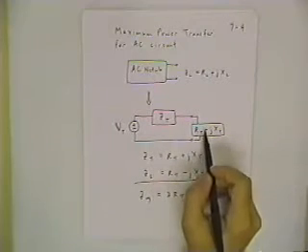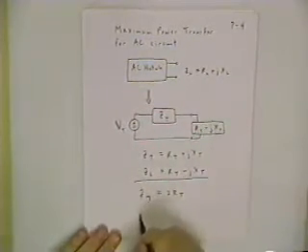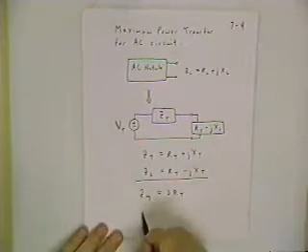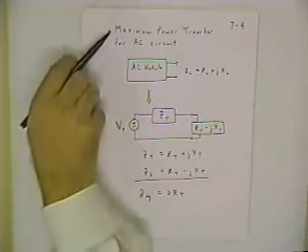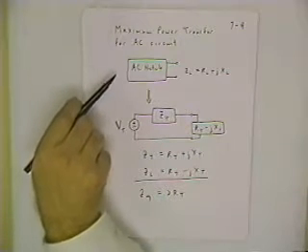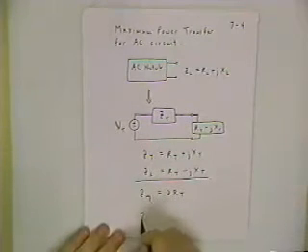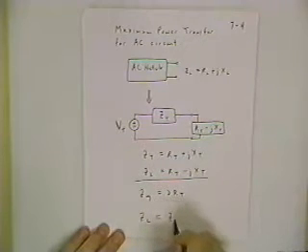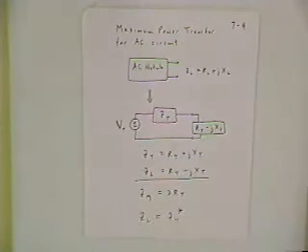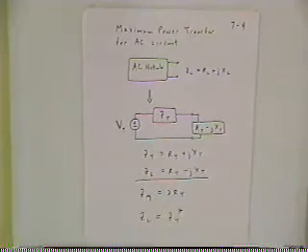and you do that by attaching not the Thevenin equivalent, but the complex conjugate. That's what this represents. So the net result here is to get maximum power transfer for an AC circuit, if you know the Thevenin equivalent, what you do is attach a Z sub L that's equal to Z Thevenin conjugate. And that's a little different from what we did with real resistive circuits, where to get the maximum power transfer to the load, you attach the load resistance equal to the Thevenin resistance. For AC circuits, you make the load impedance equal to the Thevenin impedance conjugated, so that you get rid of that imaginary part.